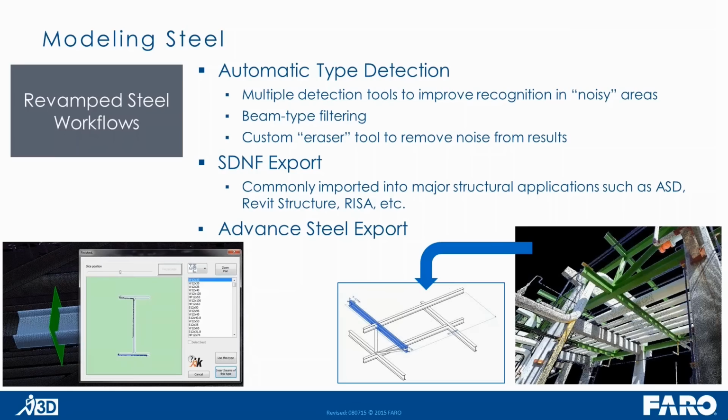Now, the last thing you can do here, and you'll see this more in the video, you can't really see it in the screenshot, but you can hold down your left mouse button and actually erase noise or disruptive data from the preview. So if you've got, like I said before, a piece of pipe sitting on top of the steel, you can erase the pipe out of the calculation and then hit the recalculate button, and it'll find a much better pattern for you.